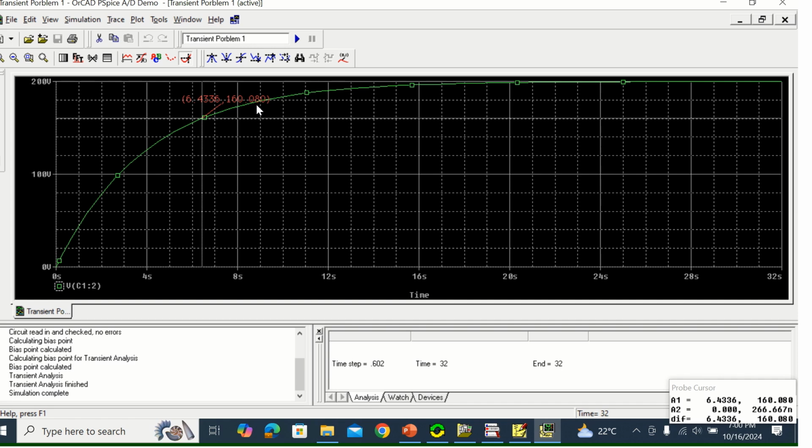The third part of the question asks what is the voltage across the capacitor after 5 time constants, right? 1 time constant is 4 seconds. So 5 time constants is 20 seconds, 5 times 4. You have to move the cursor till it is 20 seconds over here. Or you can look here, this is 20 seconds. Till here you have to move it. See, now it is exactly 20 seconds. I will mark this point. So 20 seconds is the time and the capacitor voltage is